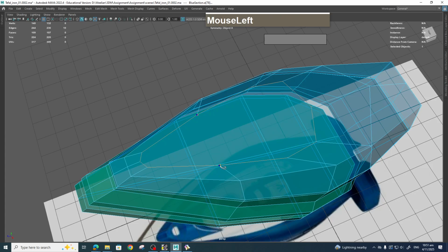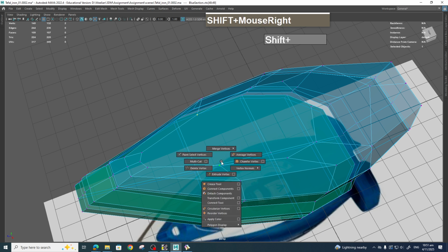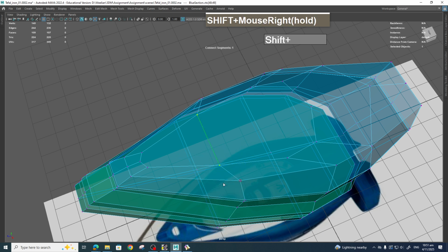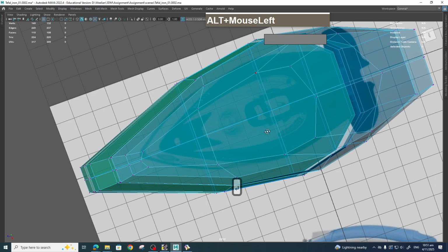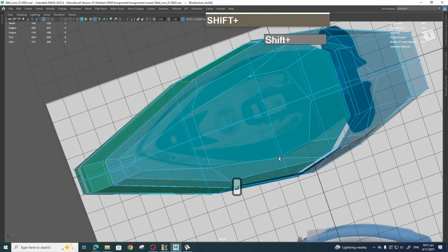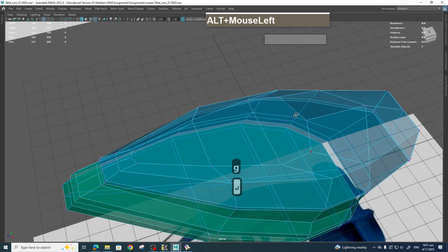Okay, let's go to level 1, and we're going to use our knife tool to cut, or use the connect tool. Symmetry is still on. Let me just Control Shift, turn it off first. I'm going to use the connect tool, so select these two opposing vertices and connect. Then this one here, remember G, enter connect.